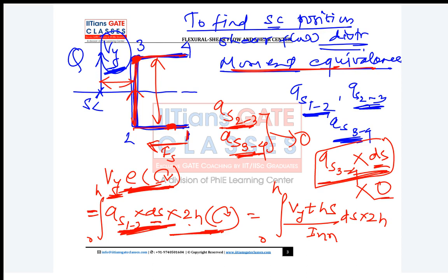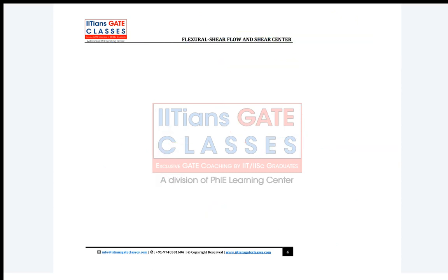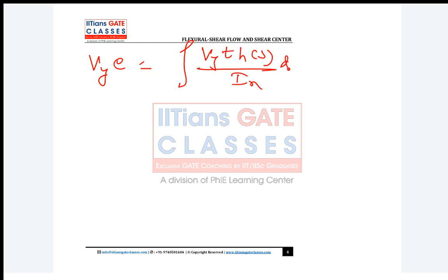Is this point clear, Akshat? We are not doing moment equilibrium. We are taking moment equivalence. Okay, so guys, what we found here: Vy into e equals the integration of Vy t h s upon Ix ds into 2h, integration 0 to h.